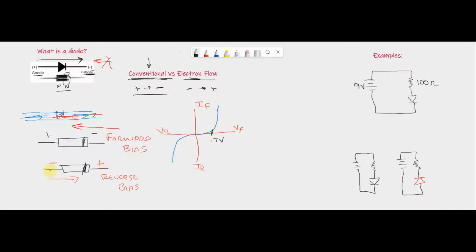Now, in the case where we reverse the voltage and current tries to flow the opposite direction, we get kind of the same thing where the voltage is reversed and then all of a sudden it starts conducting. This tends to be a bad thing. This is where we could damage our diode because we're forcing a current through it the wrong direction. Now, what this value is right here depends upon whatever diode that you pick. It can be more or less. It's not necessarily 0.7.